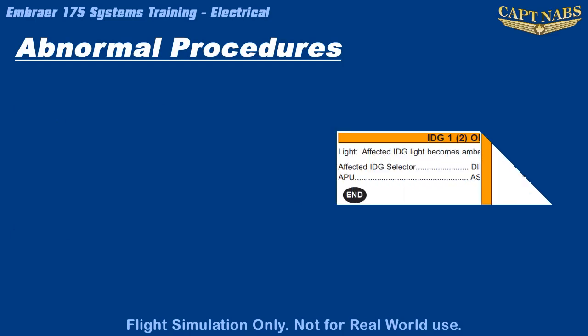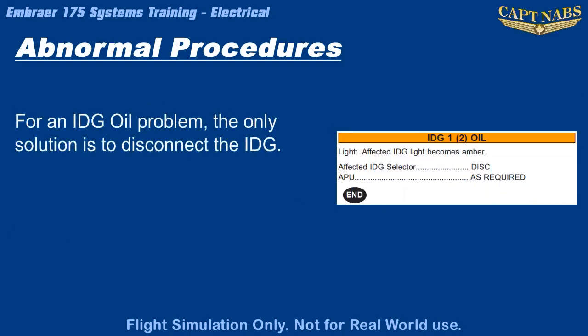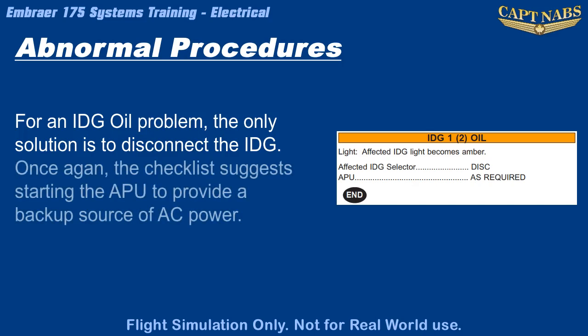IDG oil messages indicate that an IDG is experiencing high oil pressure or temperature within the constant speed drive. The only remedy is to disconnect the IDG. Be sure to confirm the correct IDG with the illuminated panel LED to avoid disconnecting the wrong IDG, as this step is irreversible in flight.